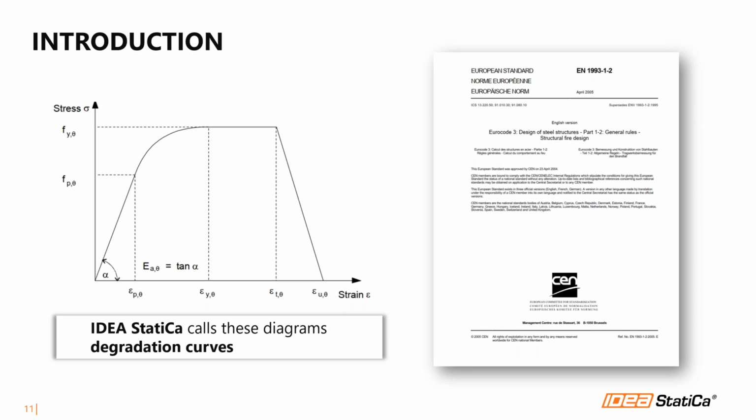part. And let's start with the stress-strain curve, since IDEA StatiCa uses a materially nonlinear analysis that employs a stress-strain curve. For elevated temperatures that occur during fire situations, these stress-strain relationships must be modified according to the provisions of this part of the code.